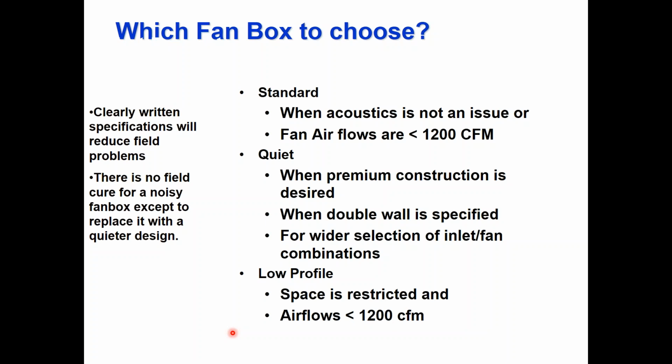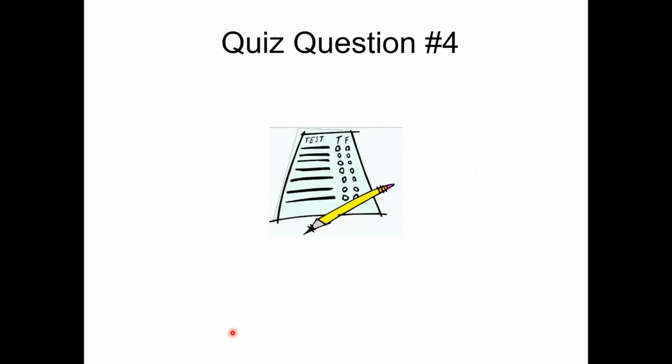You can use either one of these, and it's usually designer preference. The main big differences are going to be constant airflow on the series, which means constant sound, and I don't have to worry about my diffuser selection for turn down. Parallel means that I'm running it more for a heating dominated scenario, and I don't need the constant CFM. I can tolerate the higher sound levels.